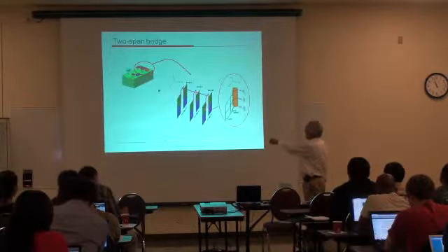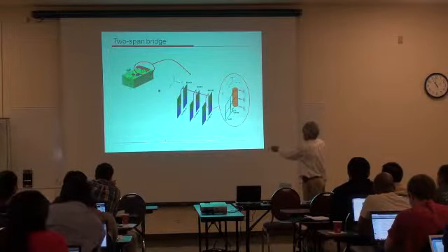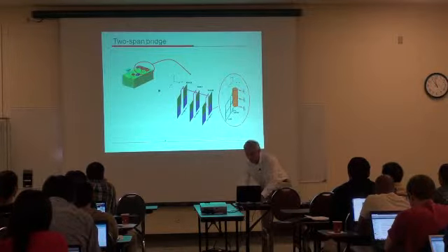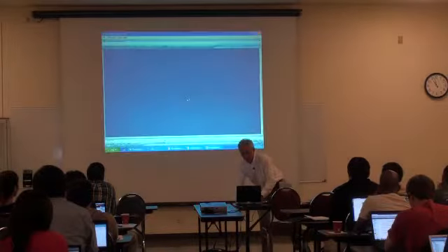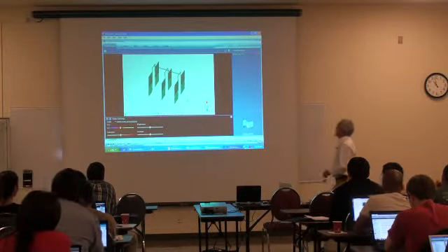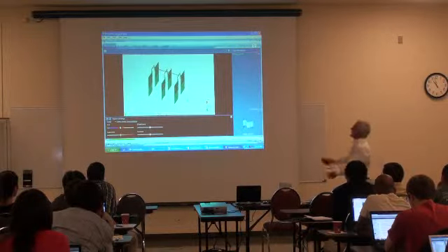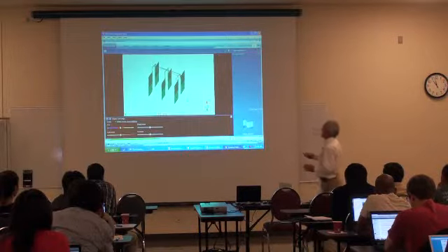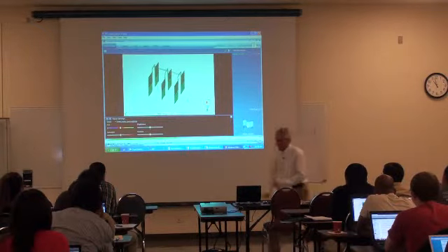Three-dimensional, but you have these columns of soils that impose a deformation in that direction. In the perpendicular direction, I just put some springs. And very simple. I'm not saying that this is the best one. And if you look at what you get if you impose deformations here, you see at least the three-dimensional response of the bridge is captured. Now the question is, how good is captured this response?